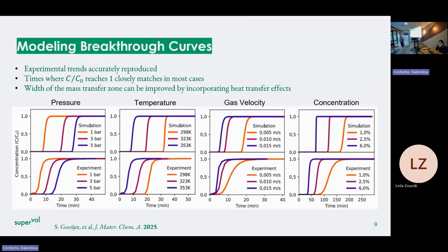Then the dynamic, the breakthrough curve modeling. So here we've performed simulations of breakthrough curves of CO2 in helium for different pressures, temperatures, gas velocities. And the experiments are shown on the bottom and the simulation on the right. So this was done with our numerical software model. We could very accurately reproduce experimental trends, and also most of the time the time at which the inlet concentration was again reached.